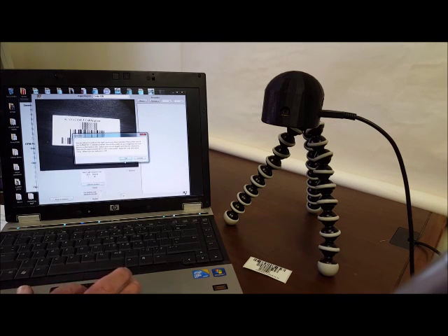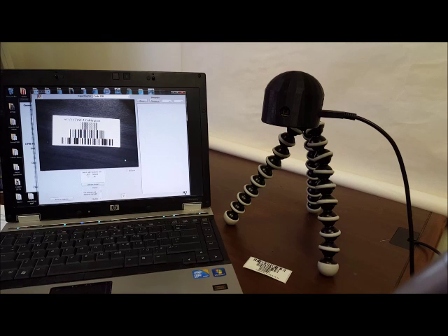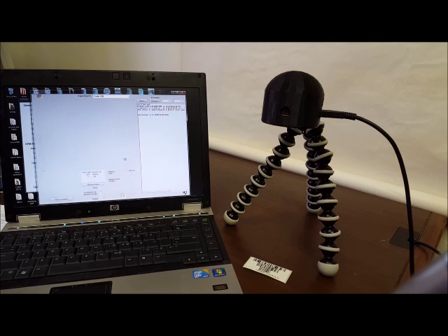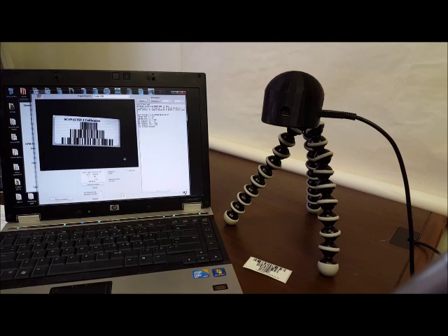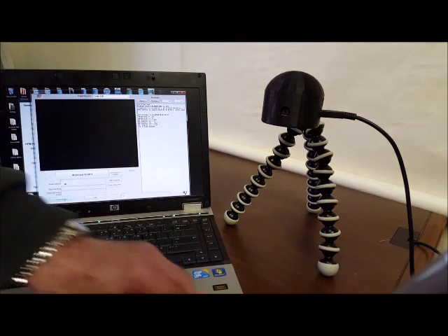When you do this, what's actually happening is that the various lighting conditions and distance, things of that nature, are being looked at by SCANALYST, and various settings are being made to regulate the exposure that the camera gives to these test images. So it's adjusting that now. It has finished the adjustment. Calibration is now complete, and you can return to the inspection and place your target image in the viewing area.